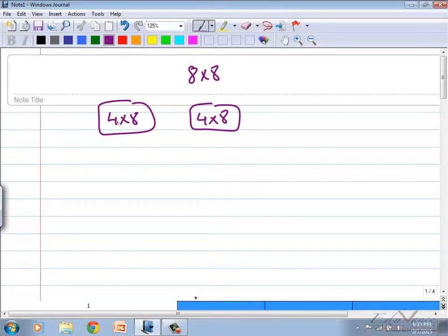But hold on, I have to now choose between these two. So now I will need a column decoder. Correct? Now my row decoder, how many locations are here? 4. So I need a 2:4 decoder. Now I have 3 bits of address. How many locations do I still have? 8 locations. The number of locations has not reduced. It is 8.